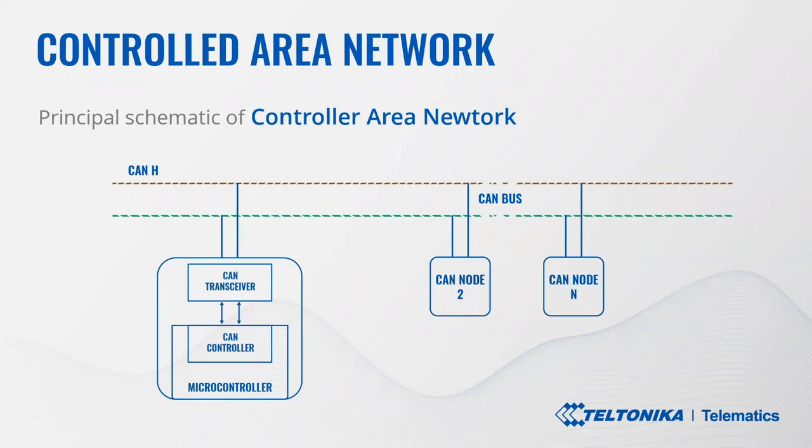In straight cable, noise current is flowing in the same direction, but when the cable is twisted, in some parts of the signal lines, the direction of noise current is opposite from the current in other parts of the cable. So in such scenario, noises are many factors lower than with an ordinary straight cable. As a conclusion, we highlight this point to notify you that you will find a twisted pair representing the CAN lines where connection will be made.